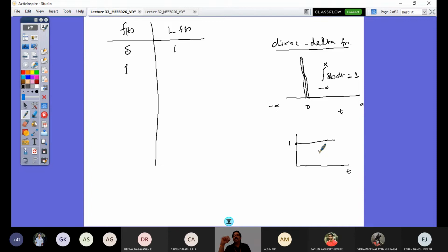If your physical system is subjected to sudden shocks, then the Dirac delta function as an input, and examining its output, is appropriate. If your response is gradually varying, then a function called the ramp function is a good function. So these are some standard aperiodic signal input functions that are generally considered in any transient and steady state response analysis of your physical systems.